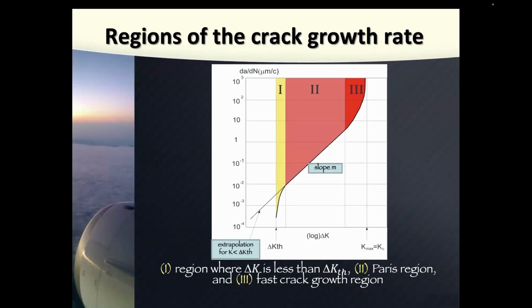So the second phase is where we have a stable, for some reason this sometimes lazy is working, sometimes not. Okay, never mind. So in the second phase or stage, we have more or less stable crack growth, which means that rate of crack growth is more or less constant. And you can see here on this logarithmic diagram, we can find the slope of this because it's almost straight line in this graph.